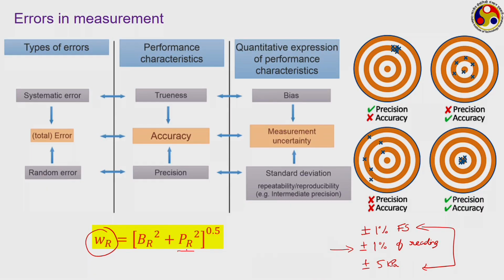What we did there is basically the propagation of uncertainties in the final value. We are going to see how to estimate the precision error for a particular measuring device in today's lecture. But before that, this bias error or systematic error we are not going to talk about, because they generally appear because of wrong calibration or wrong information provided by the manufacturer, or maybe you have a correctly calibrated instrument, but with long period of use or with wear and tear, it may develop some kind of bias error.